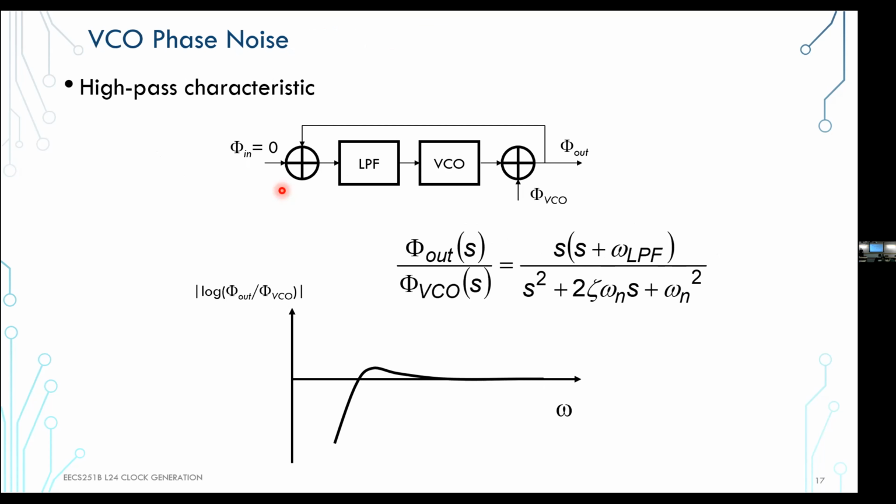Now, another thing that we talked about already was the VCO and its own noise, right? We talked about its own thermal noise, the supply noise impact on the VCO, etc. And so it's useful to think about, okay, how does the loop react to some phase noise of the VCO that the VCO injects into the whole loop. In that case, it's injecting it, I'm showing here at the output.